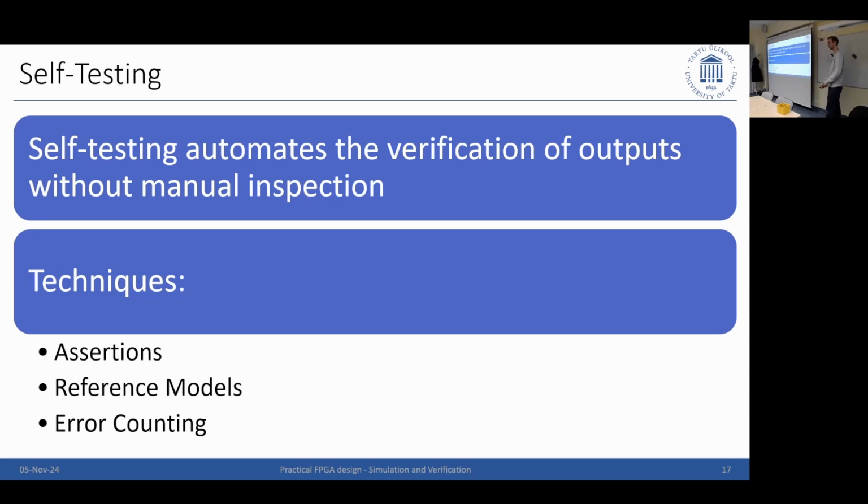So if I have an encryption, a checksum, or image processing, I implement this the same as I do in FPGA, in my Python, and I will get the response for every one of them. I run them in parallel or sequentially, whatever, and I compare one to the other, and then I know this design works correctly. This is especially useful for algorithms because you may have different test images, and asserts will not work anymore. Just simple as it is.